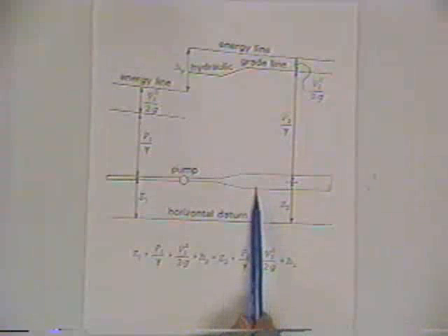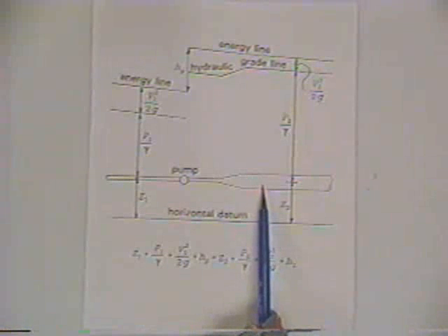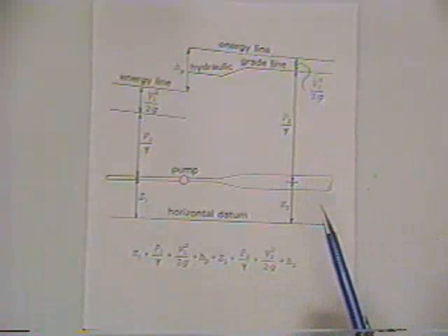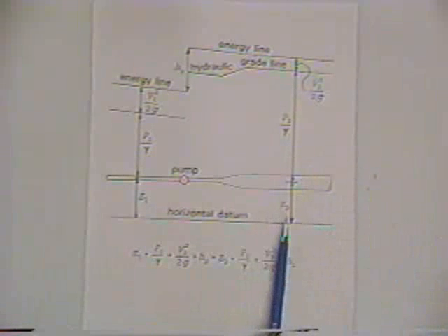And so if you come over here and you change the diameter of the pressure conduit, that's going to change the velocity and thus change the velocity head. If you change the velocity head, there's got to be a change someplace else. This is an accounting system. Whenever you add velocity head or subtract velocity head, it's got to come from either pressure head or elevation head.